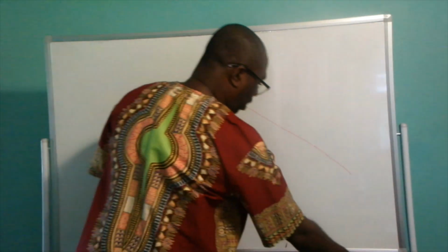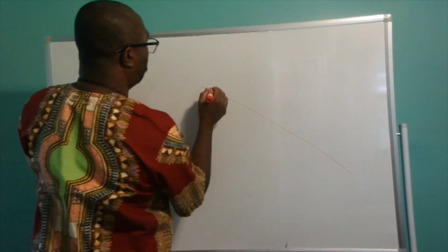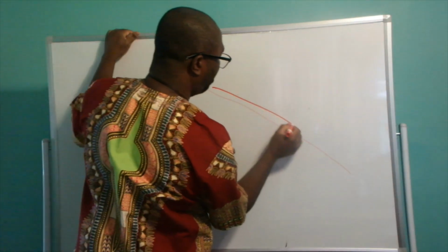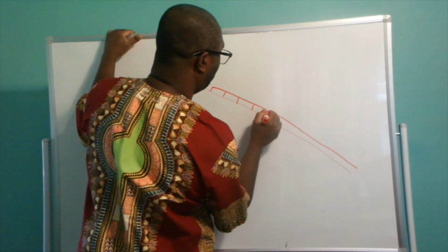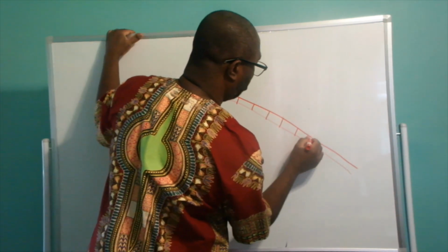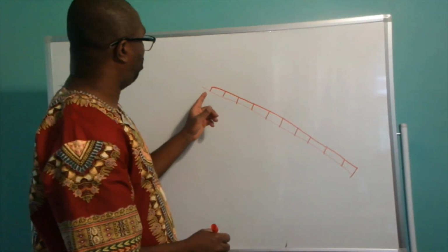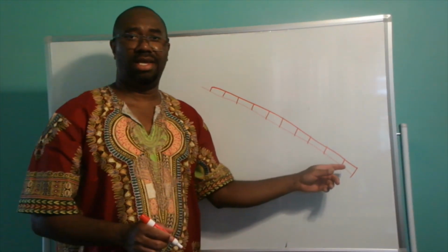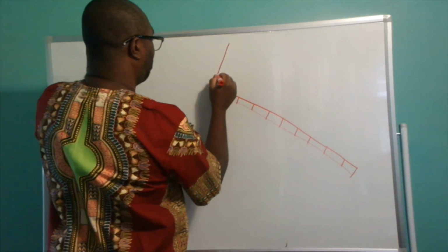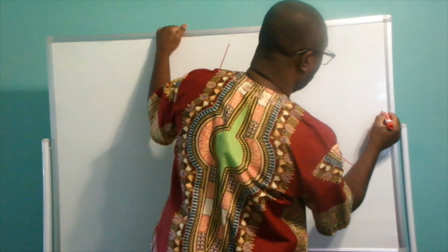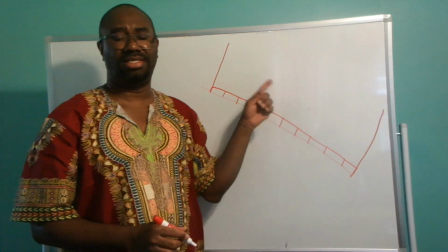So you do not want to place your block work on your land like this, because what you are going to end up with is a slanted wall. So your wall is going to go up like this, right? And that way it is not appropriate.